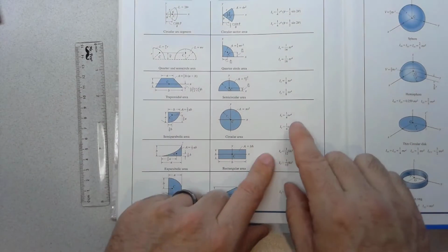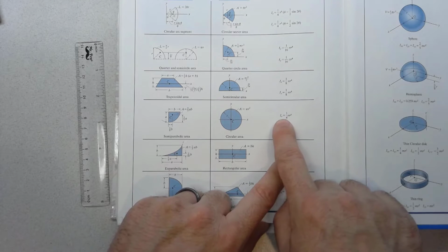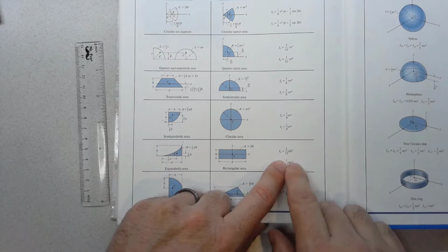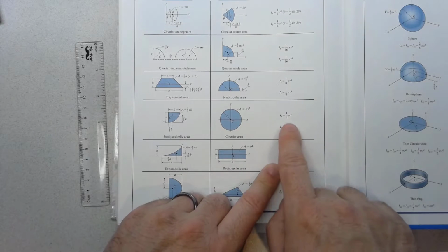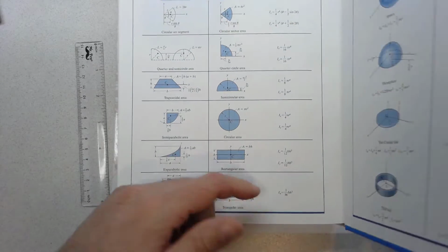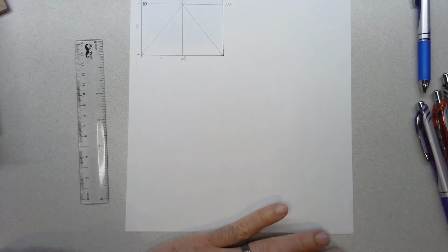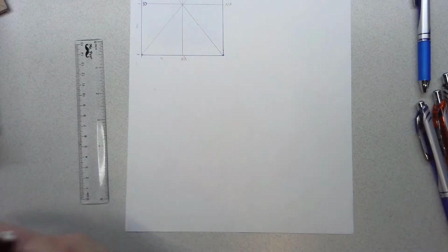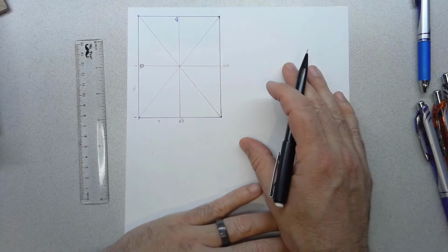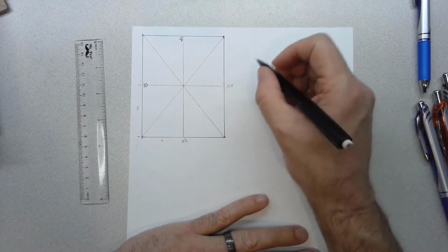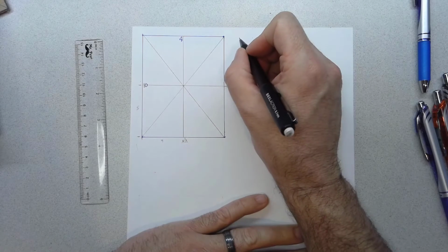Okay, let's get back to what we're talking about. So common equations for bending moment of inertia is Ix for a rectangle, 1/12 bh cubed. For a circle, 1/4 pi r to the 4th. Okay, so if we want to find composite, or let's start with a really simple one. If we're looking at that original rectangle that we worked with before here, and let's say we're bending about this axis. That's a key thing to talk about.